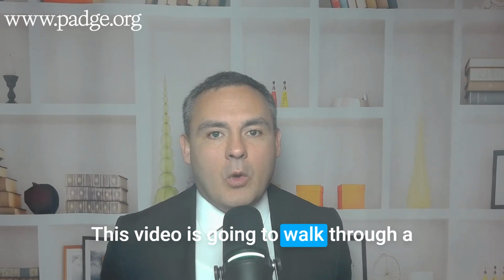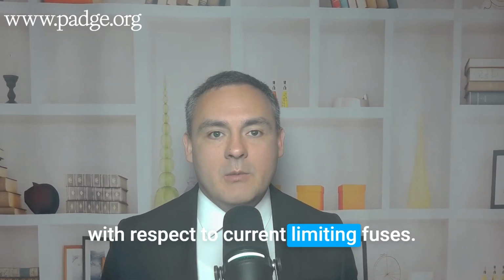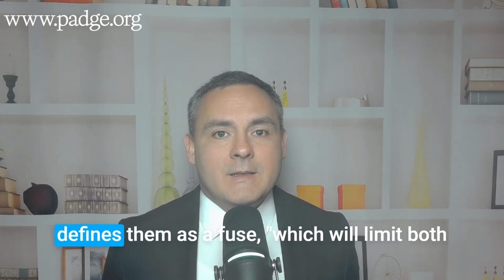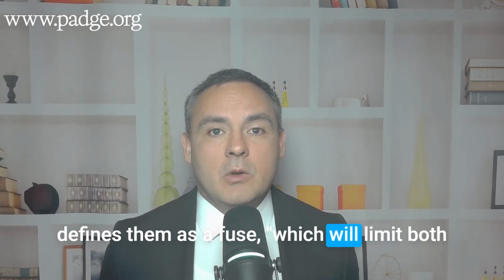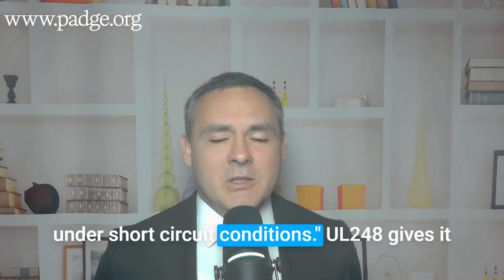This video is going to walk through a special method for arc flash calculation with respect to current limiting fuses. Merson, who makes current limiting fuses, defines them as a fuse which will limit both the magnitude and duration of current flow under short circuit conditions.